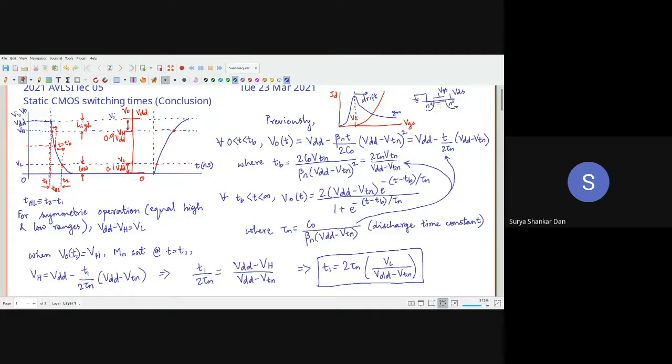Now before the channel is there, that means in the subthreshold conduction, before VGS reaches VT, what will happen? There is no channel, okay? Then how will the electrons flow? The electrons will flow due to diffusion, because diffusion is a process which is always there. What is diffusion? It's like that perfume bottle experiment which we studied in our school days.